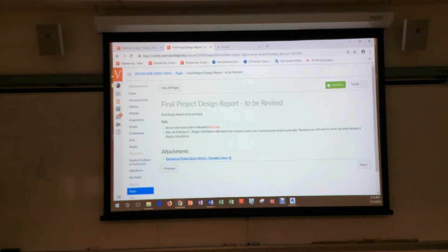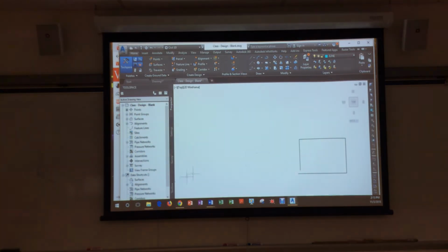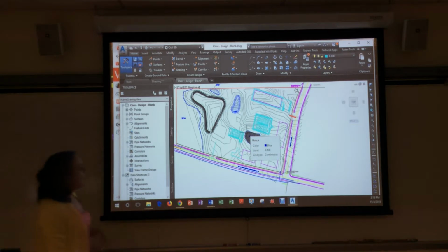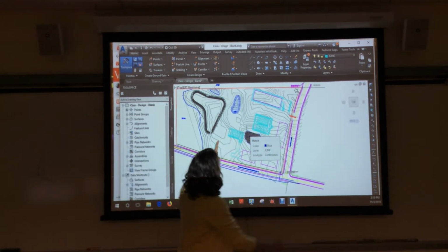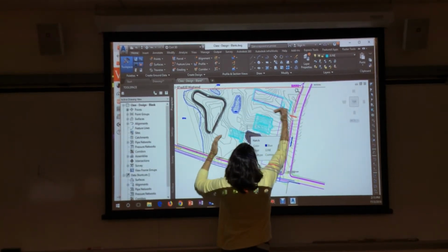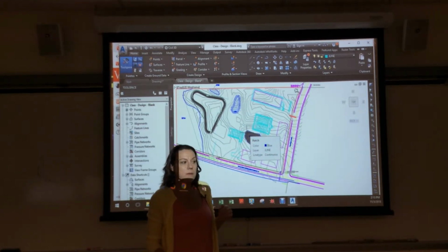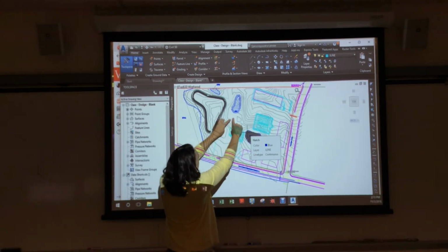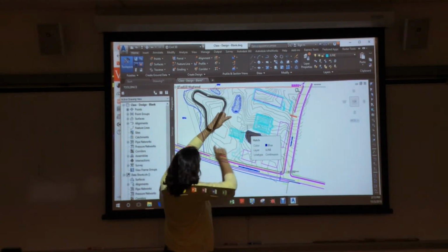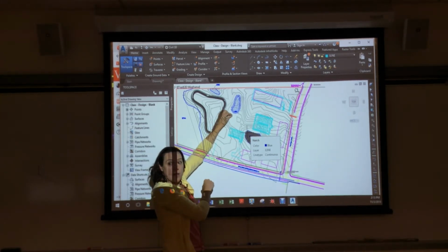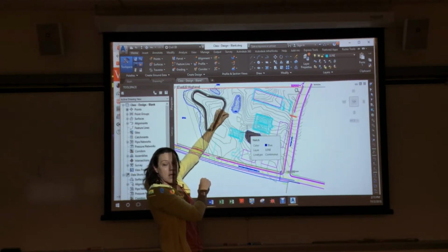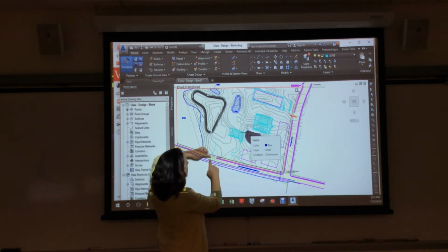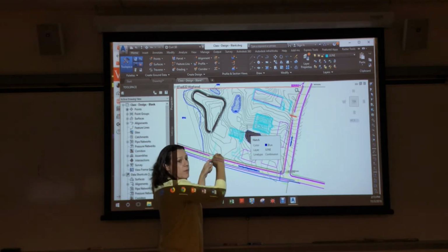Oh, let me get this up. Okay. We're going to bring in a little bit of hydrology and hydraulics right now. You have a road coming in here and a road tying in here, right? That's what our plan is. At this point right here, if I put a high point here and sent the road downhill and downhill, that would not be good because of the drainage.